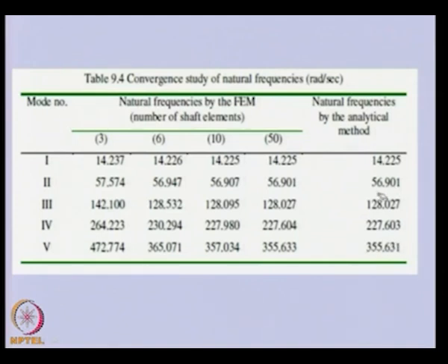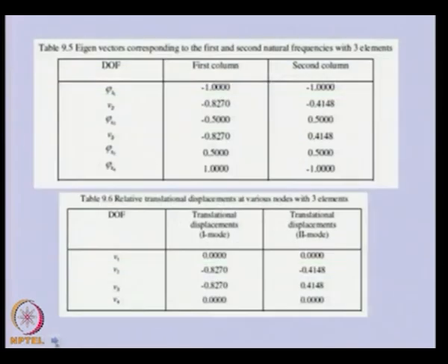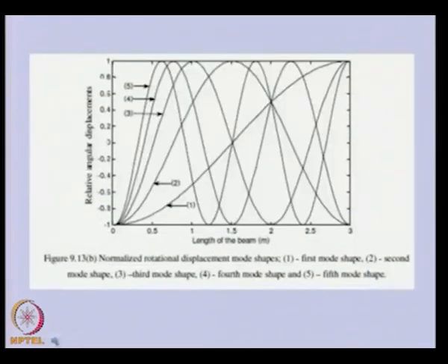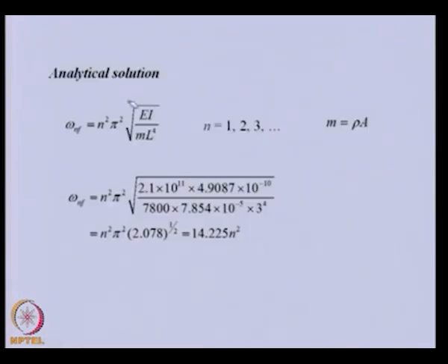And for calculation of this, this was the analytical expression for the natural frequency, where n equal to 1, 2, 3, 4 we can substitute and get the natural frequencies. So basically natural frequency is given by this. For the simply supported beam case, we need to put 1, 2, 3, 4 one by one here to get the closed form or analytical solution of this particular problem.